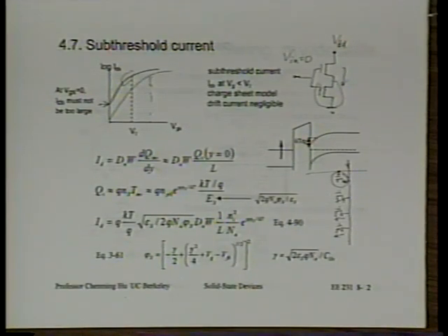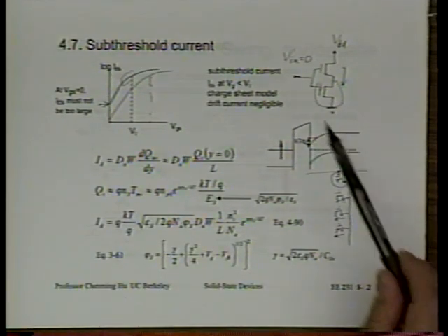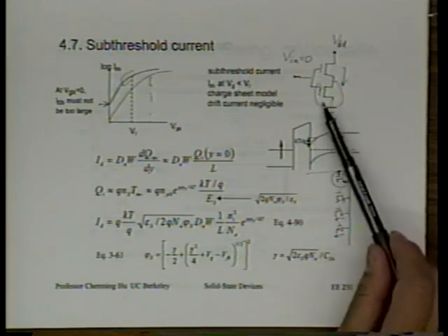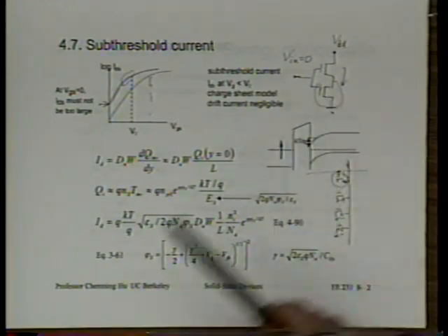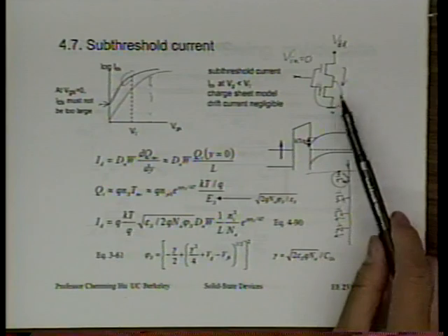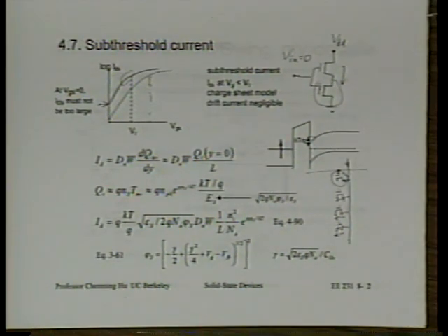One thing we can actually say is that what makes a transistor, as opposed to a resistor, let's say, is the fact that once we put 0 volt on the VG, we can count on this device taking on very little current, no matter what VD we put on this drain. All right?